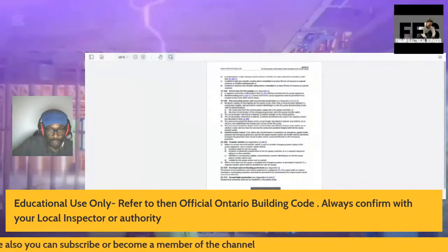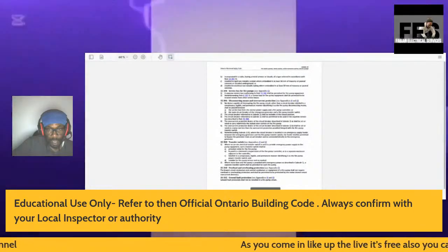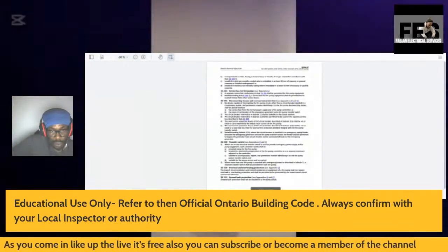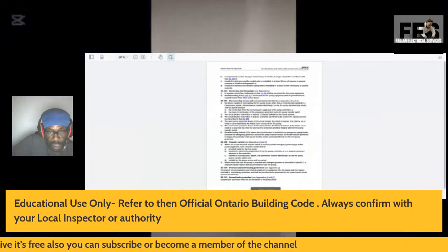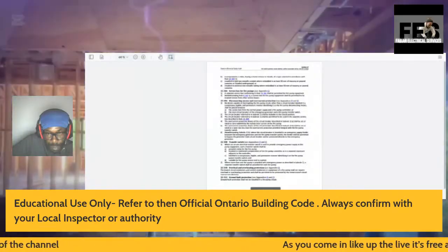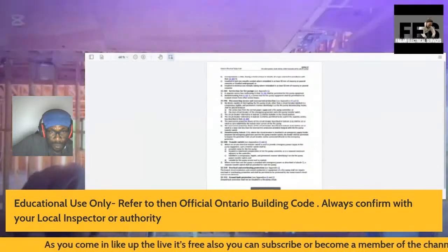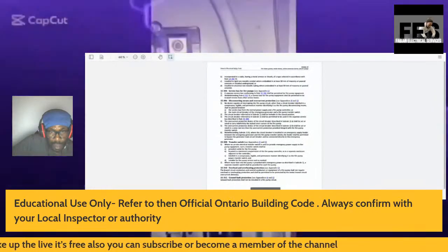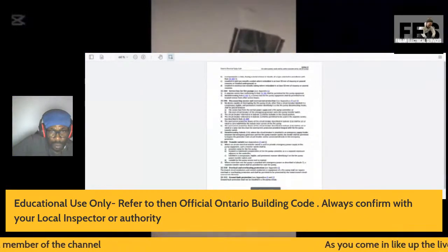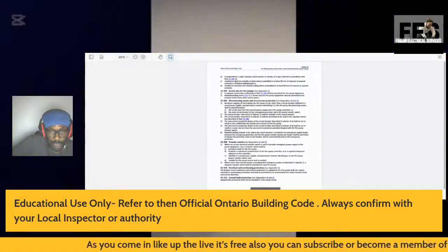Disconnecting means and overcurrent protection. No device capable of interrupting the fire pump circuit, other than a circuit breaker labeled in a conspicuous, legible and permanent manner, identifying it as the fire pump disconnecting means, shall be placed between the service box from the normal power supply and a fire pump controller, or the main circuit breaker of the emergency generator and a fire pump transfer switch.